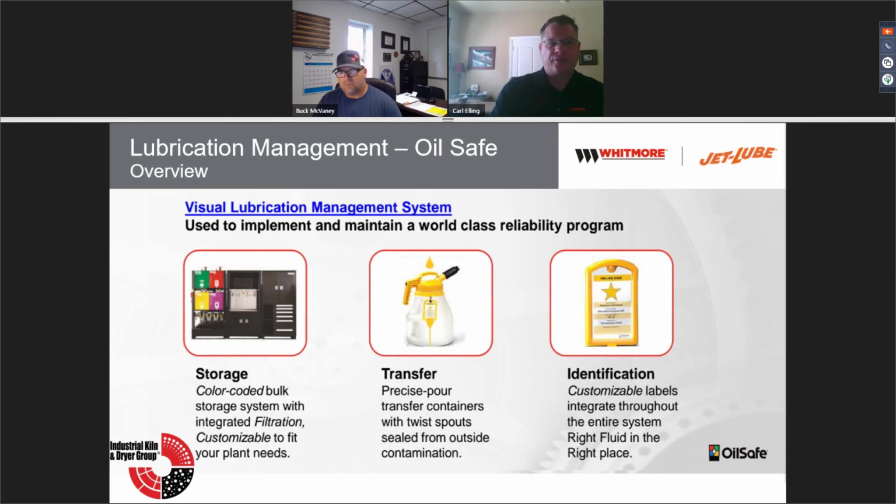Just for a keynote on this one, you'd be surprised about this, but you don't start at the big bulk system. I always thought you bought the big bulk system and then you bought all the piddly stuff afterwards. It's actually opposite. It was really kind of interesting to learn this, but you start identifying the loop points on the assets first, because that's where all the errors are being made. And it's nobody's fault, if you will, because we all make mistakes. We're human, but this is where the wrong grease is being applied in the application, or the wrong oil, wrong viscosity of oil. It's not on purpose.